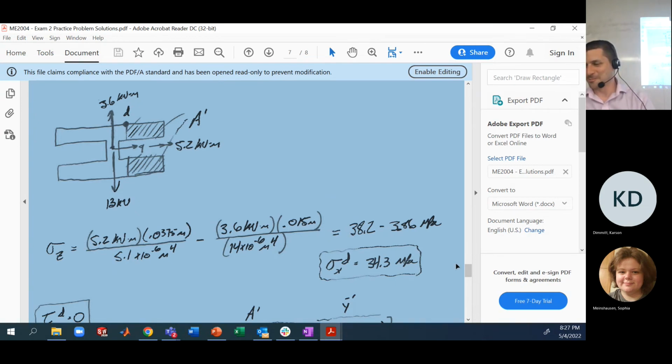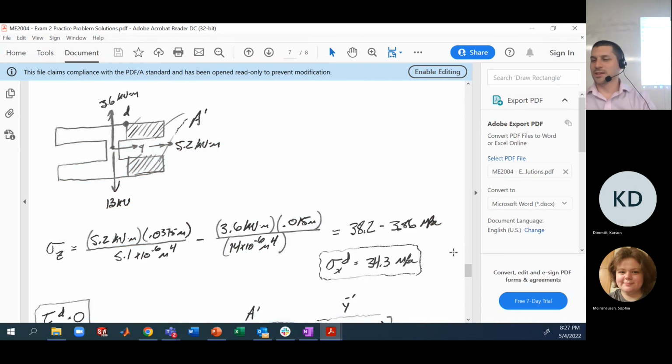Man, not a good day for me. Yeah, so these should both be in compression. Actually, no, the 5.2 is tension. That was right. Okay. 3.6 will give compression. Bend it around that 3.6, yes, definitely compression. 5.2, bend it down because we're trying to bend around it downward. Yes, that will give tension. So correct, there should be a plus sign here. This is correct as written.